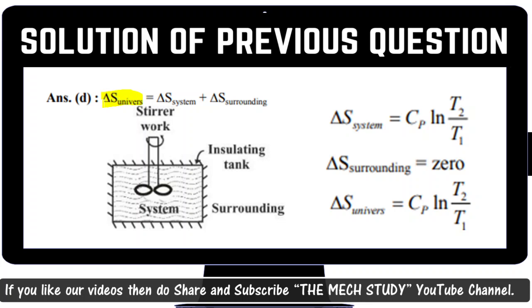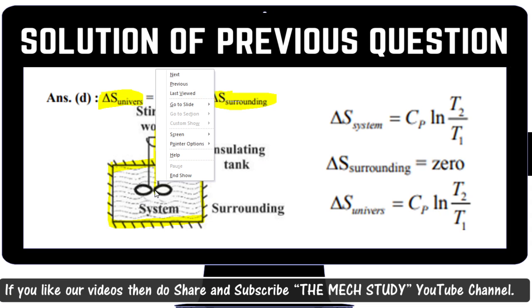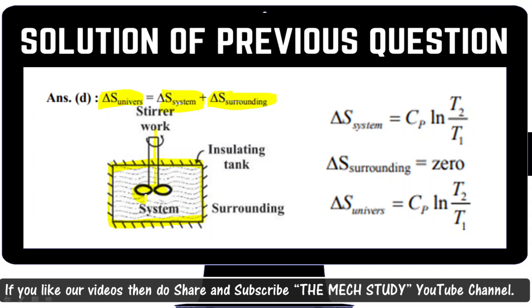The change in entropy of the universe is equal to the entropy of the system plus the entropy of the surroundings, if you remember this formula. So you have one system, and this system consists of a stirrer which is providing the work over here. These are the work done on the system, and this beaker is insulated outside, so there is no heat transfer. So delta Q, that is Q, equals 0, we need to put it. And consider the surroundings as outside, because we consider the system in the insulated tank. So for the system, if you remember the formula, it is Cp ln of T2 by T1. For the surroundings, they haven't transferred any heat, so the surroundings term is going to be 0.